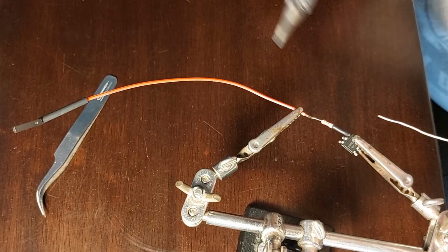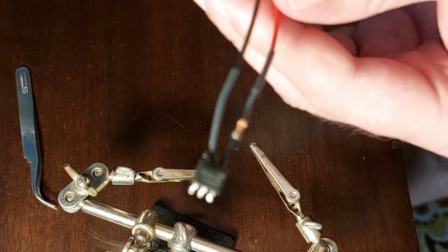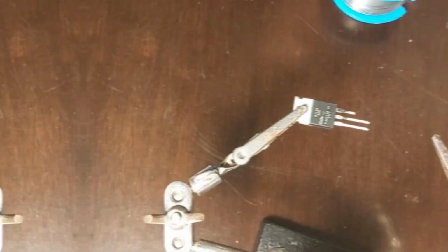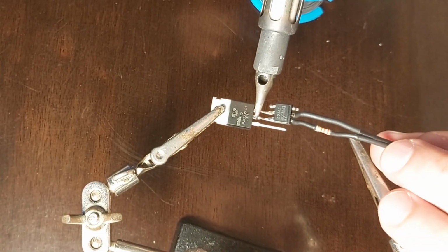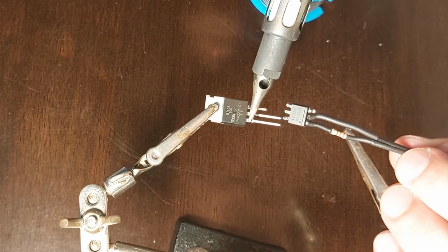If you think it's a bad idea, then I guess you might be right. But you will see for yourself in a few moments. So I soldered DC input wires along with a limiting resistor to the opto-triac and attempted to solder it all to triac terminal 2. And at this point I already knew that there would be problems.